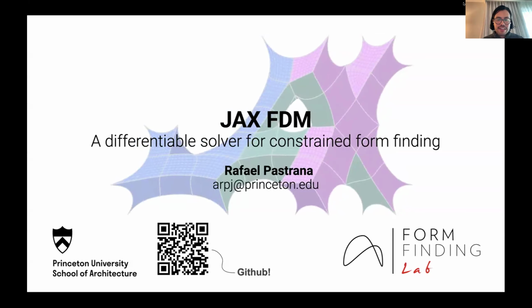And so for constraint form finding, which is the real goal here, what we actually need to do is to solve an inverse problem that, unlike traditional form finding that goes from left to right, from parameters to solution, here what we actually want to do is to say, okay, form finding, what I need is to find an efficient shape that looks like this other arbitrary shape. And the question we really want to know is, what are the right parameters that are conducive to that?